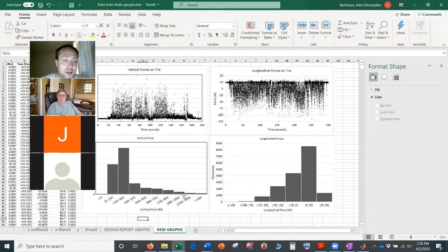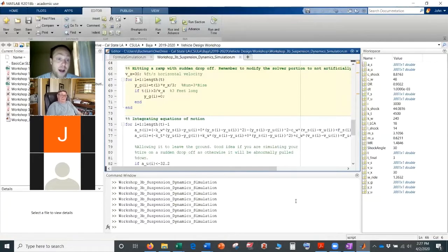We go up to maybe 1,000 pounds force. But I think that's an error in our instrumentation maybe. This might be a little bit higher than we expect. So I think maybe the other data is more reliable in the 600-700 pound range, kind of the 5G corner range. But putting all that together, you can make an argument for the judges about why you pick the different forces for designing your different components, basically, right?